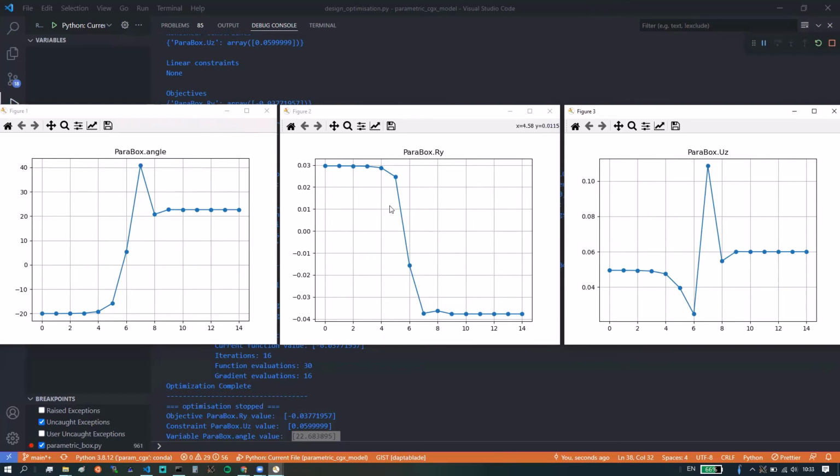And if we then look at our optimization objective function, here we have a very nice evolution. It's very slow initially as well, which corresponds to a change in variable which is very small initially. And then as soon as we go into negative angle rotations for the material, we also see this bend twist coupling, this negative bend twist coupling kicking in, and we have negative rotation angles, and it converges again towards a constant value, towards minus 0.04 for the later iterations.